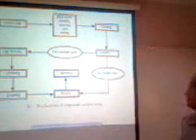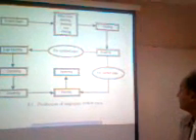You can see from the cotton bale, we first feed this material into the blow room, and then from the blow room, the next process is the carding. From the carding, it comes into the drying. From drying, it has two lines of production. If we want to produce a combed yarn, we will have to take it to the comber, or if we want to produce a carded yarn, we directly take the material to the roving process, from where it is directly